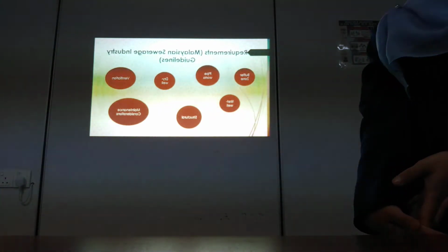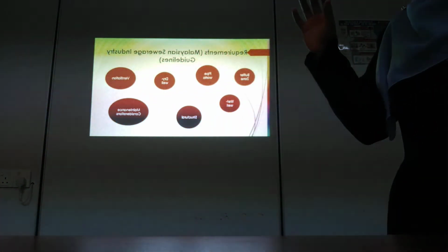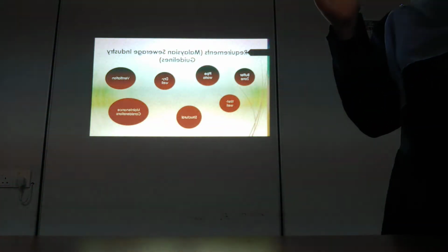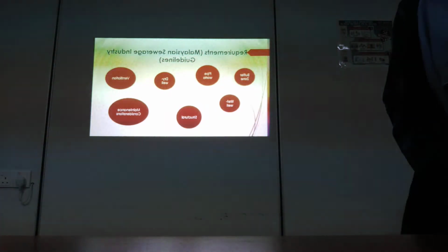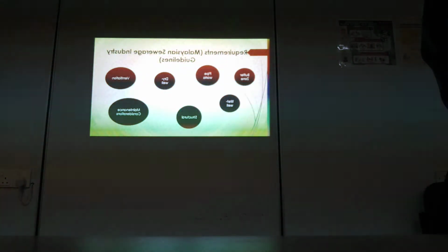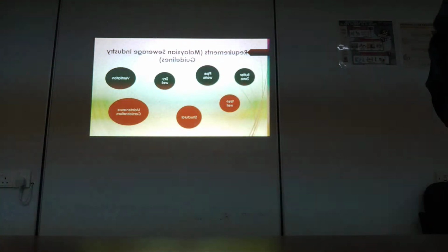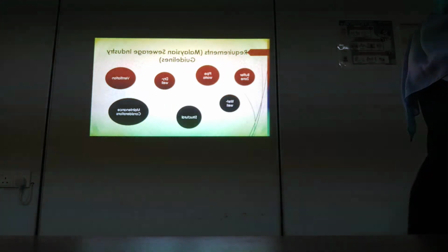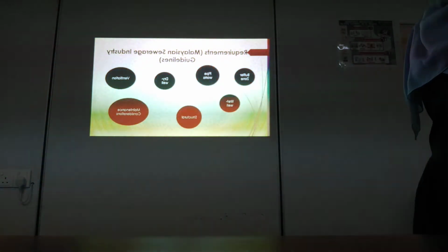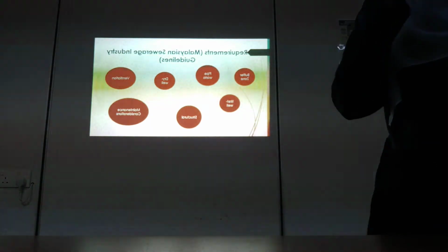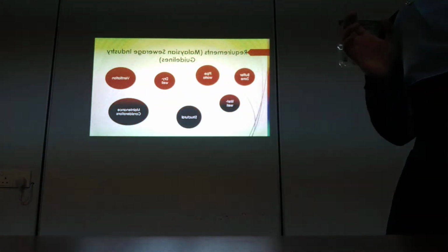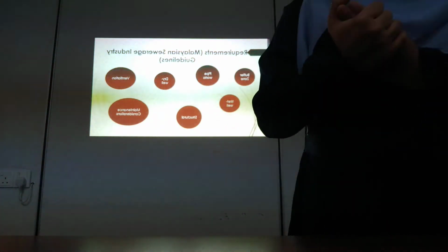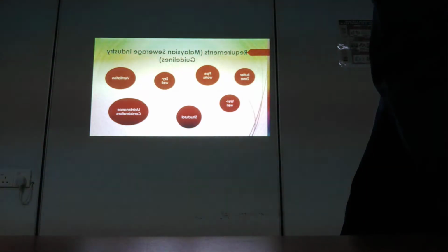A wet well must provide access, and if it exceeds 6 meters, the ladder must change direction. That is important. Then ventilation: there must be separate ventilation between the dry and wet well. Maintenance requires availability of spare parts, appropriate lifting for heavy equipment, and a complete set of general arrangement and sectional drawings available at the site.